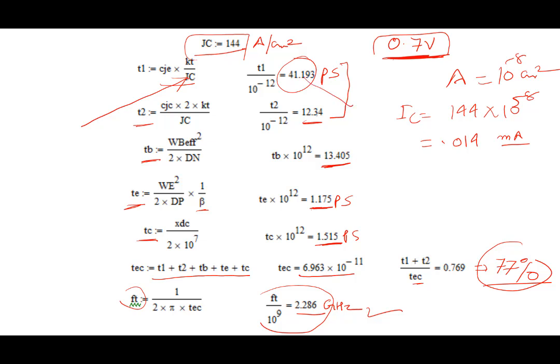This should become 1.2 picosecond, right? And then these become small, and then I will be limited by this. So a simple strategy, for whoever works with bipolar transistors: if you want higher speed, try to operate the transistor at higher current. And you can see why. For a given area, if you increase the current, you're increasing the current density, and your transistor will become faster, right?